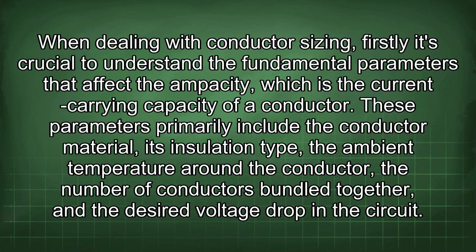When dealing with conductor sizing, firstly, it's crucial to understand the fundamental parameters that affect the ampacity, which is the current carrying capacity of a conductor. These parameters primarily include the conductor material, its insulation type, the ambient temperature around the conductor, the number of conductors bundled together, and the desired voltage drop in the circuit.